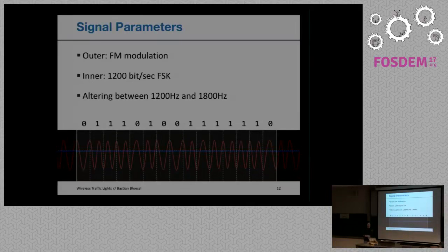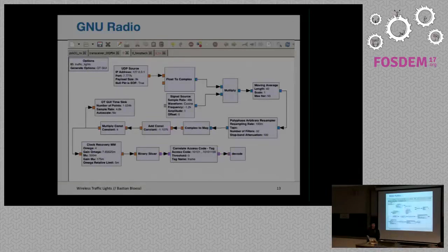And with this, I manually decoded the preamble. I think Spectrum also has some possibility to decode the signal, but I just manually wrote down the preamble because this is what I needed in GNU Radio. And with all this knowledge, I can come up with a simple GNU Radio flow graph to decode this thing. Actually, now I'm claiming that it's so simple and I'm just doing that step, but I think this is the step that might be the most challenging for several people. The message is that maybe this is the most stupid way to decode the signal, but it's just what I came up with.